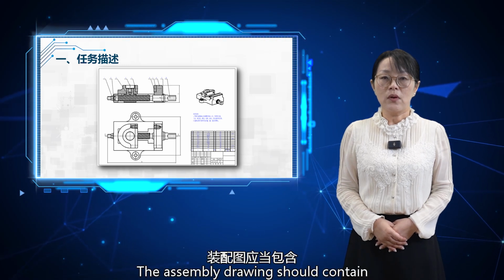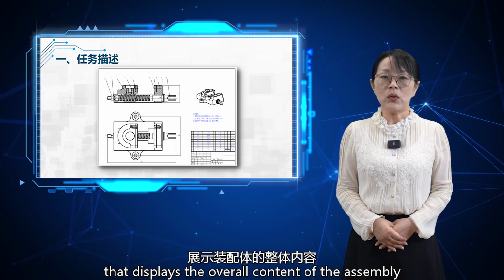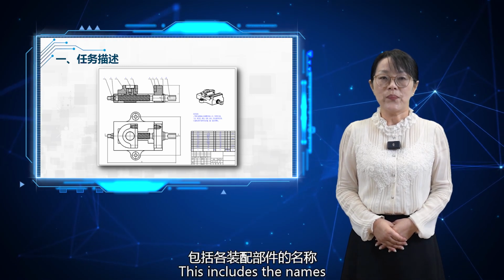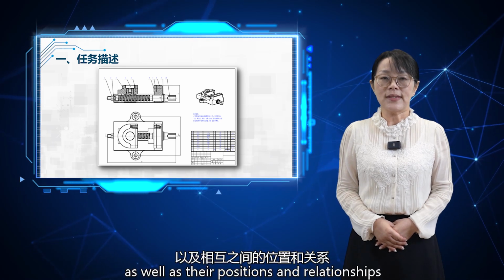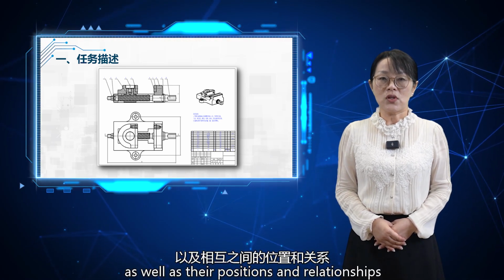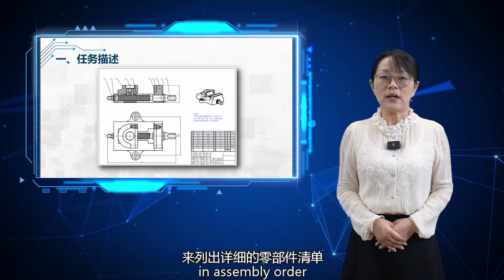The assembly drawing should contain a general layout that displays the overall content of the assembly. This includes the names and numbers of each assembly component, as well as their positions and relationships. It should also list a detailed parts list in assembly order.